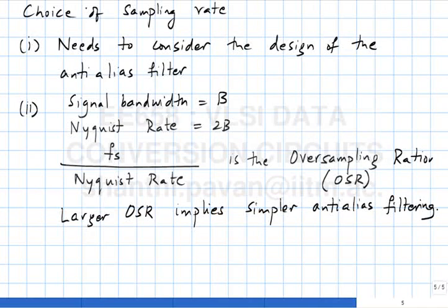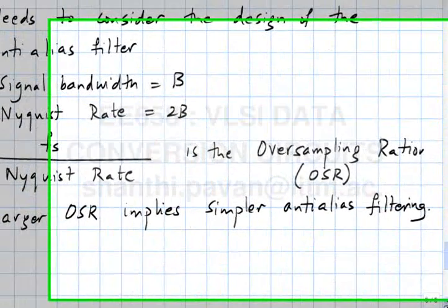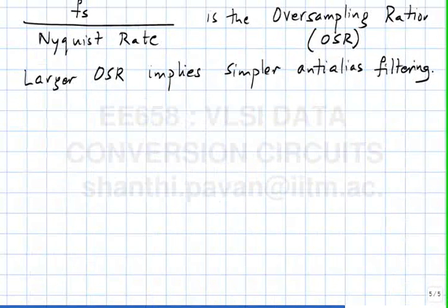So a classic case is wideband oscilloscopes, where the signal bandwidths that they can digitize can be, depending on how much you pay, as high as 20 or 30 gigahertz. Okay, and in such cases it becomes obviously extremely difficult to oversample by a very large degree. You try to be as close to Nyquist as possible in sampling rate.